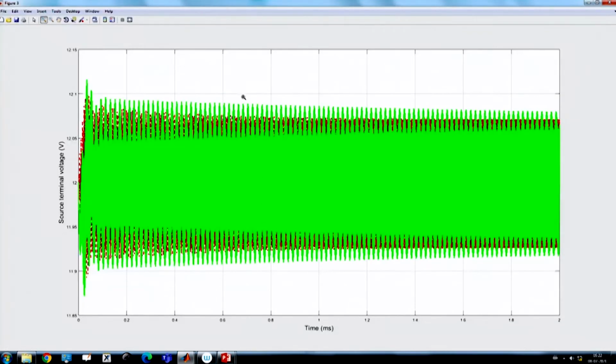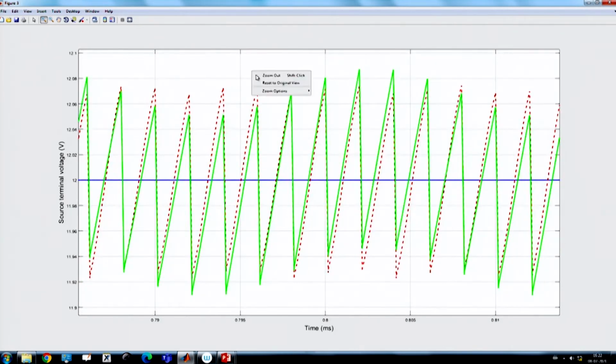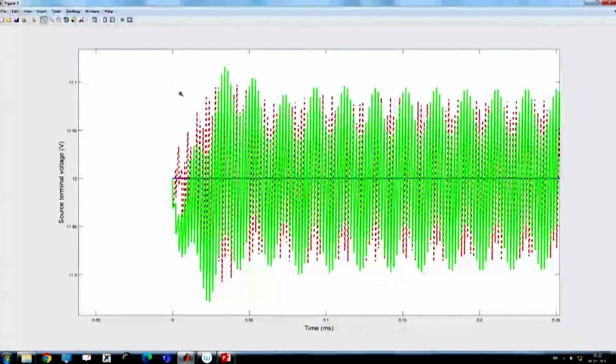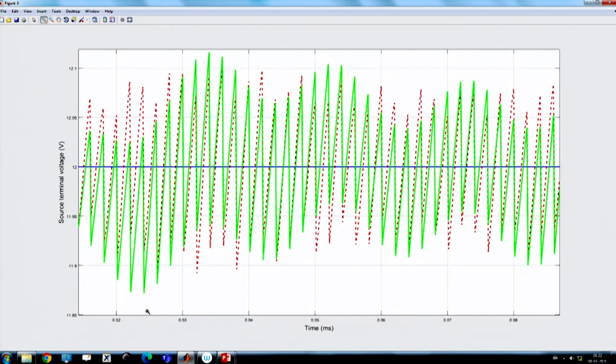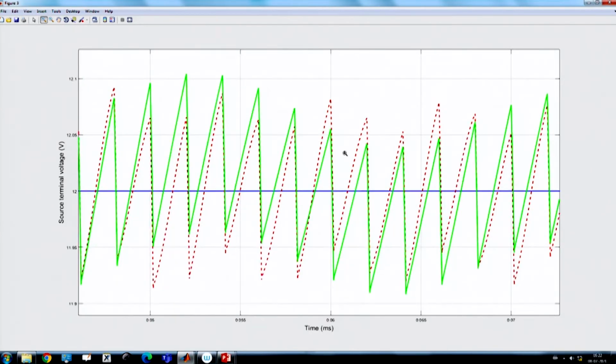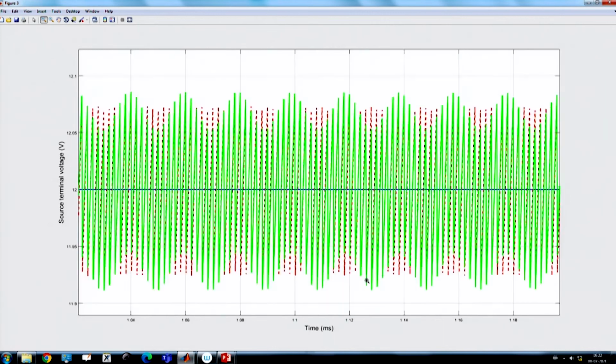Okay. So, if you take the effect, it is no longer negligible, because particularly during the input, you will see there is also a slow scale oscillation along with the switching event, and that oscillation slowly damps out because there is an LC circuit with its resonating frequency, the LC frequency. That is interfering with this event, and that is why we can see the effect due to the supply variation.